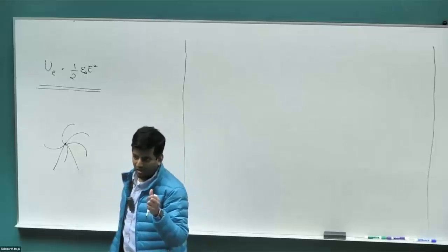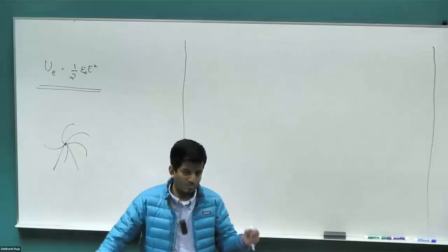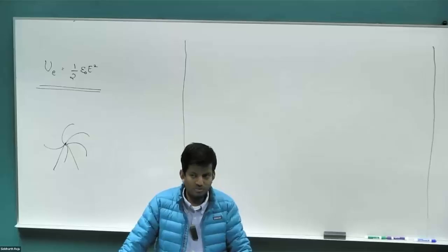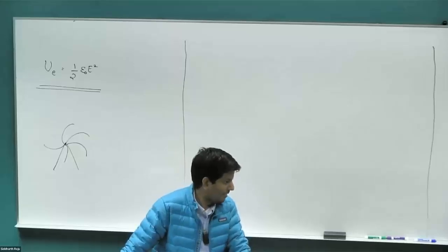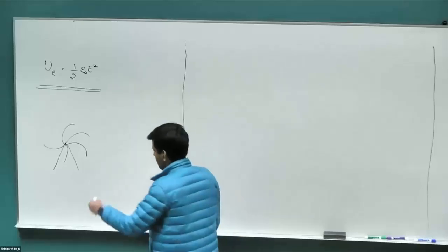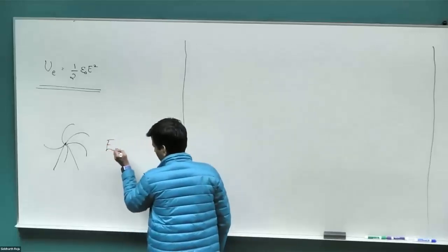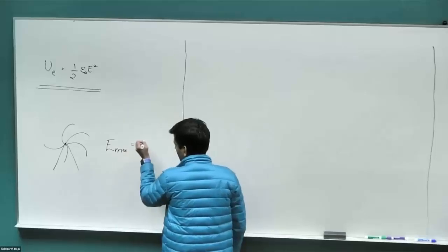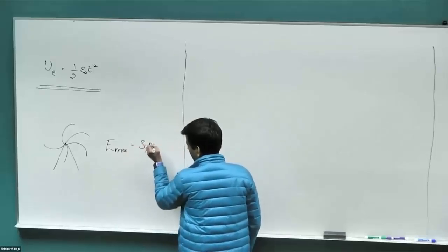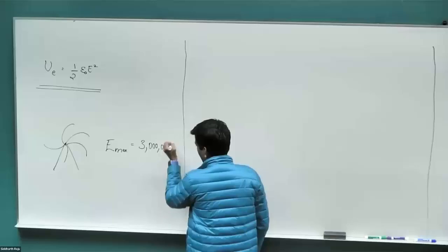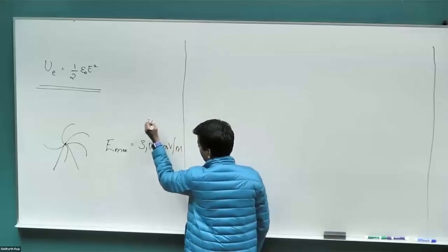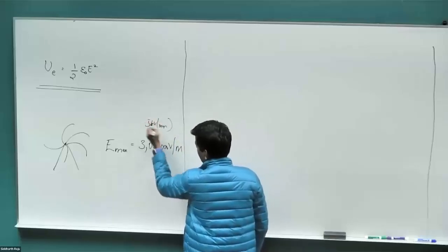All right, what was the electric field at which air starts to puncture and we get corona discharge? Anybody remember the value? Yep. You say 3 kilovolts per millimeter? 3 kilovolts per millimeter, okay. So E max for air that we saw was 3 million volts per meter, or commonly just 3 kV per millimeter.